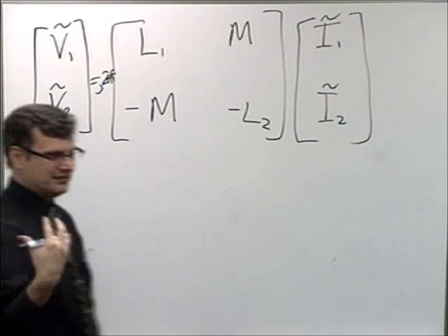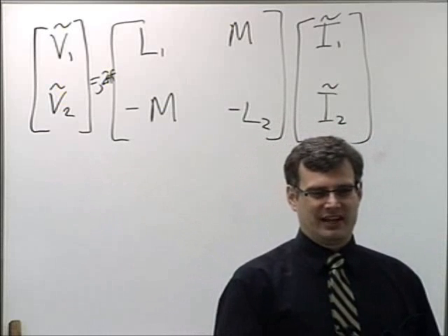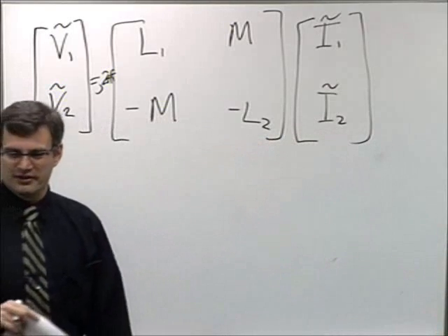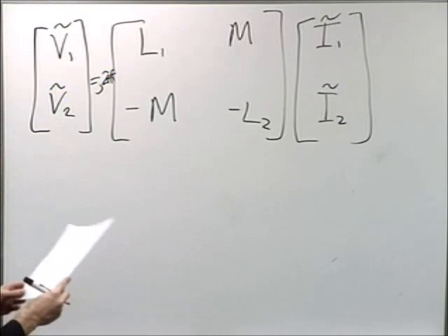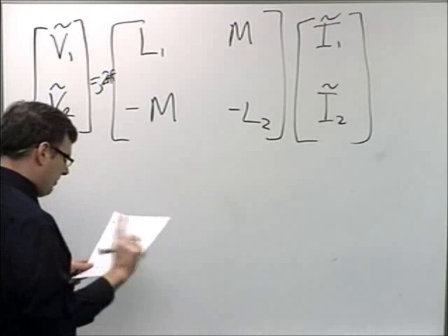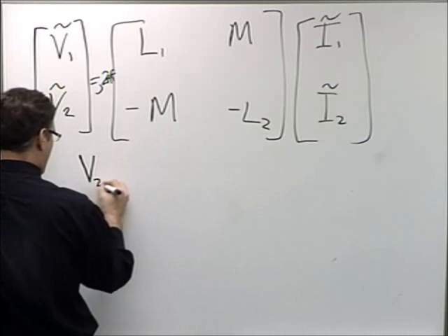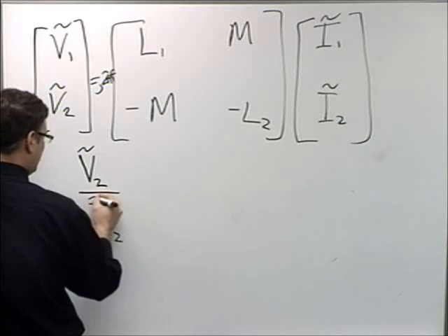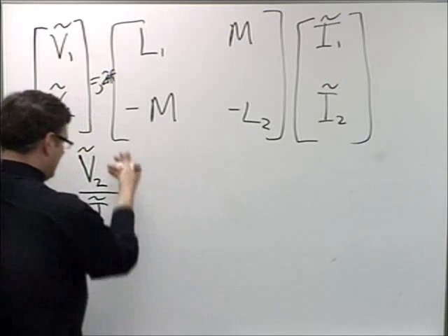In fact, this type of system would allow you to analyze a crazy complicated inductive system with like 3, 4, 5, 10, 20 coils, all sharing inductance, stimulating currents on one another. Okay, so let's break it down now. We want to get that Thevenin equivalent impedance. So by definition, in the circuit that I just erased, my load voltage on output port 2, the ratio of that load voltage to the load current is going to depend on what you connect to it. In fact, the impedance of the thing you connect to it is that ratio, right?